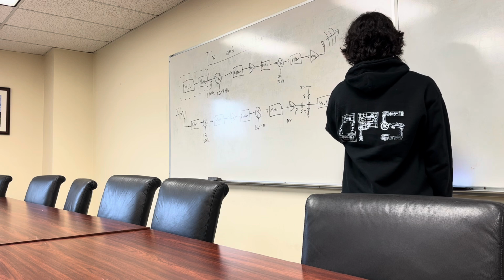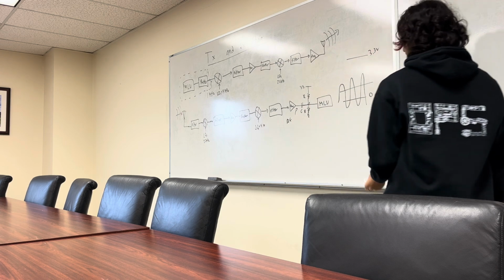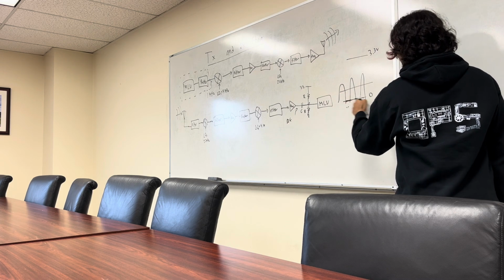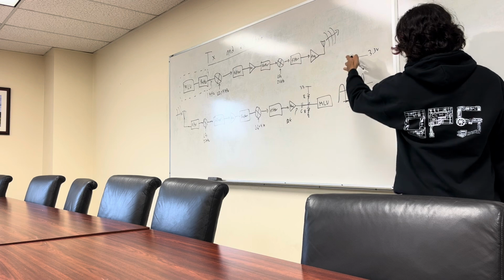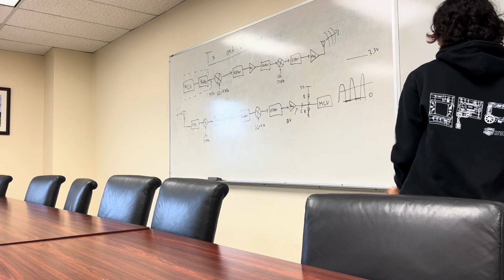If we have a signal centered here and it has a large swing, what's going to happen is it's going to get cut off. So we lose dynamic range. You're not going to see this at all, right? So we can go all the way up there, and we have no limitations here, but down here, we get cut off and lose dynamic range.